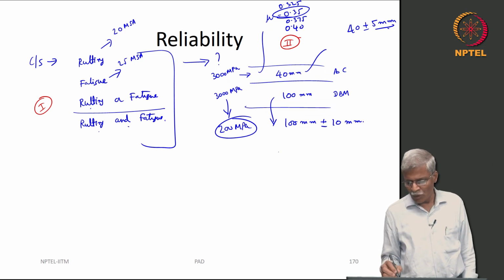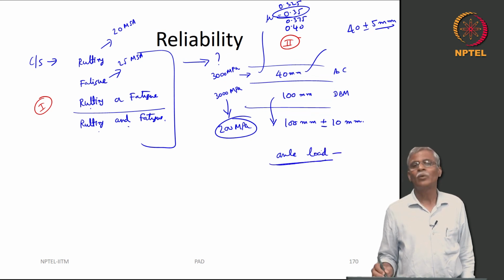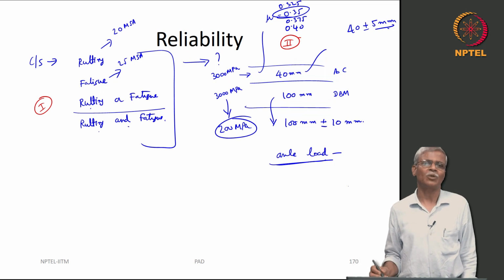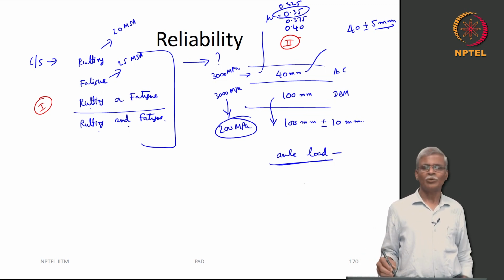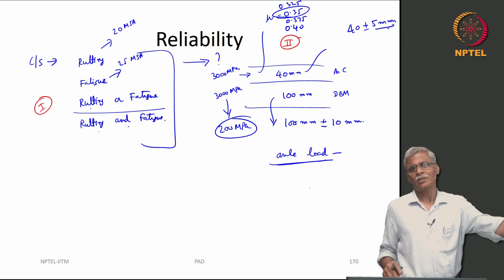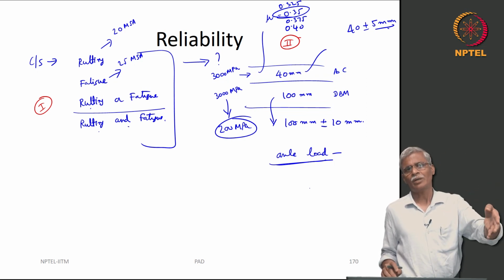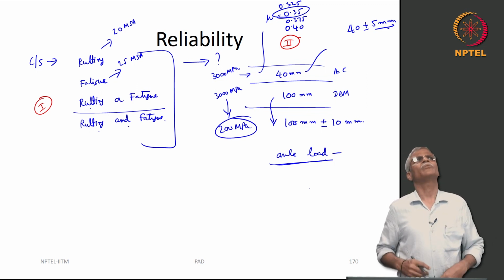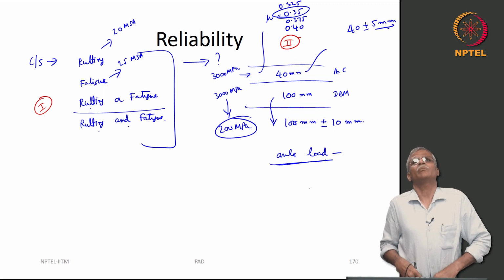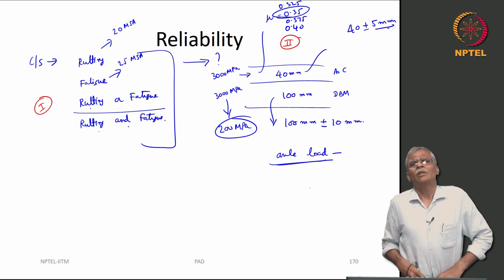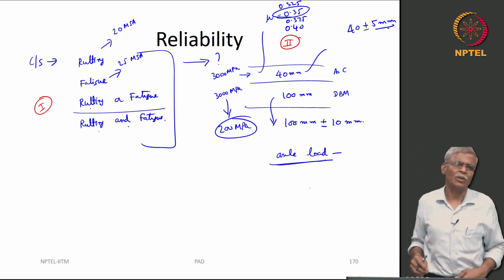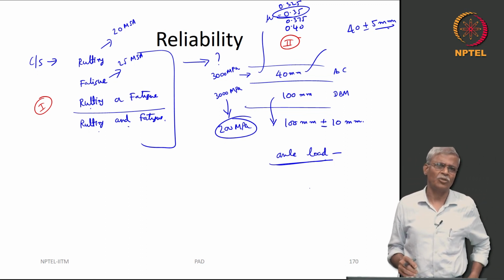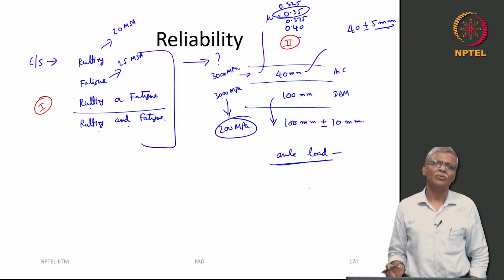And then you are doing some axial load survey, okay. And now let us say, how reliable is this axial load survey? So, you can again have a problem. So, if you link it up with whatever we discussed in the traffic part, you can fit a distribution to it, and then you can say that, okay, I am talking in terms of heavy vehicles. These heavy vehicles are going to have this much variability. This is the normal distribution that you are really looking at. How will the reliability change? Okay. So, these are all some of the interesting aspects that one can look into.